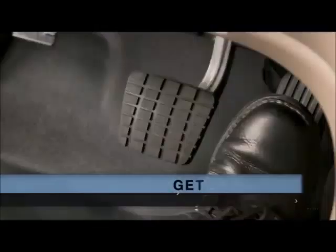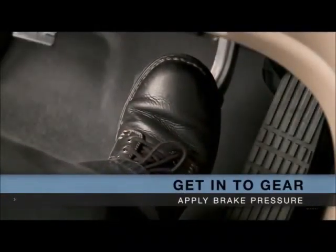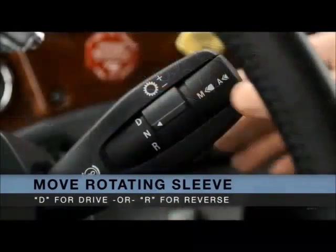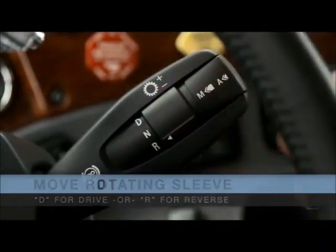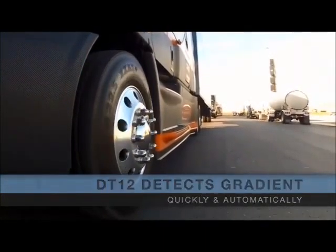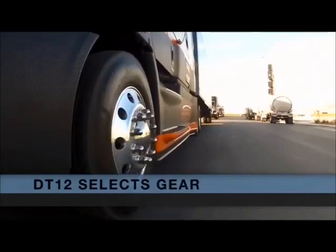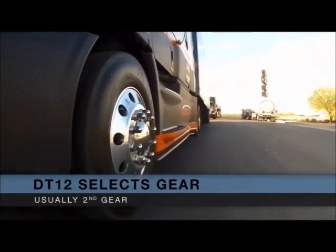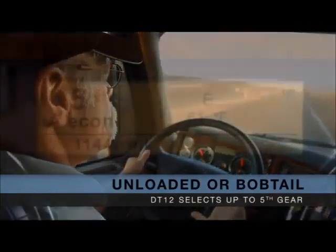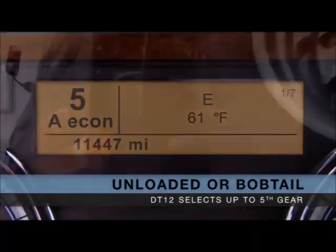To get into gear, first apply brake pressure, then move the rotating sleeve on the gear selector stalk to D for drive or R for reverse. The DT12 will quickly and automatically detect the gradient you're starting on and select the appropriate starting gear ratio, usually second. In an unloaded or bobtail situation, the transmission may select up to 5th gear to start the vehicle rolling.